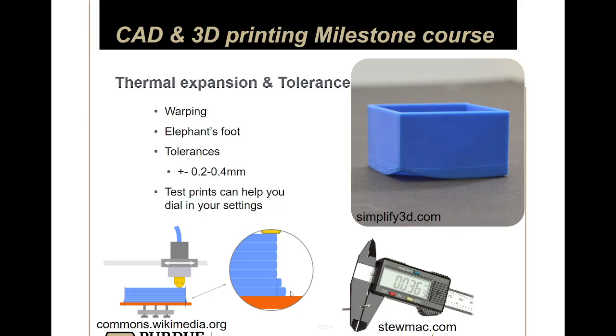And if you're making two parts that fit together, sometimes having that elephant's foot will prevent them from sliding into each other. So one thing to combat that is just having better print tolerances, having a dialed printer. But the other way to do it is by adding a chamfer into your model. You can see here that this wall was just straight up and down.